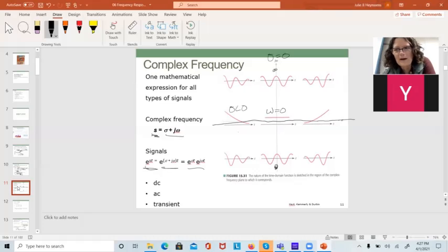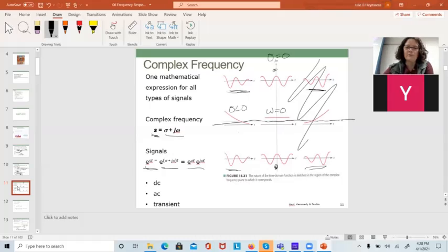down here. Now, if I combine exponentially decaying functions with sines and cosines, I get these exponentially decaying sines and cosines. These are really common, and you see these a lot in the real world. And you can also have the dreaded exponentially growing sines and cosines, which always lead to fires. Now, because there are so many problems with fires on the right-hand side of this graph, controls engineers, when they draw their diagrams, they just leave it off. It doesn't exist because I'm not going to build anything that's going to exponentially grow with time.